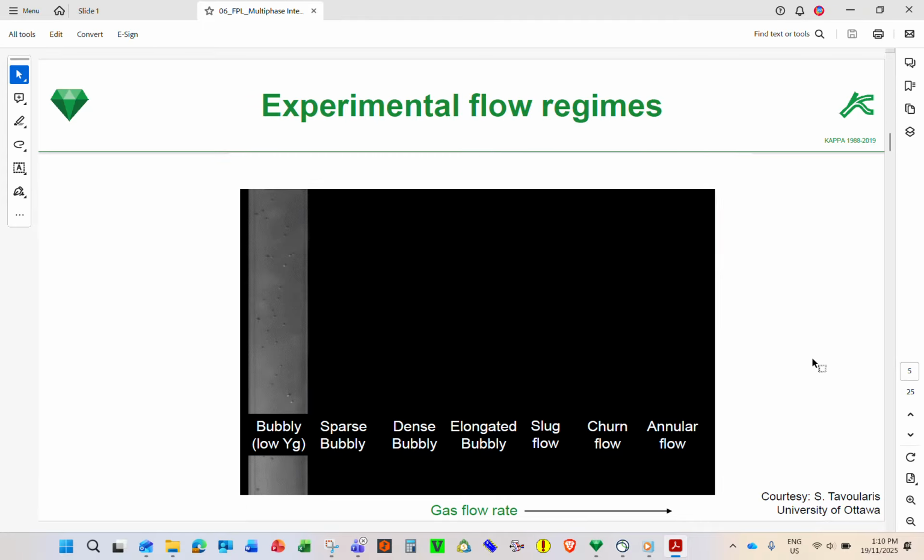Gas is lighter than the liquid, so it's going faster. So you might see bubbles of gas, and you'll be looking like slug, and a bigger slug. So you might see not continuous. Does it make the higher the gas, the higher the bubble? Yeah, higher speed, higher velocity, higher bubble, and the more gas will be a bigger bubble, and it will be like slug.